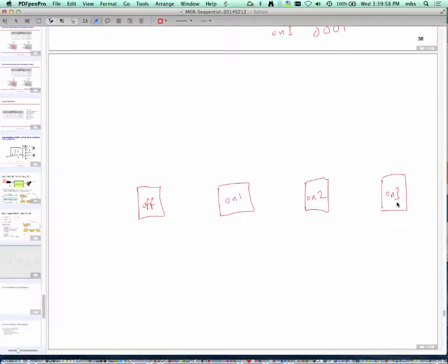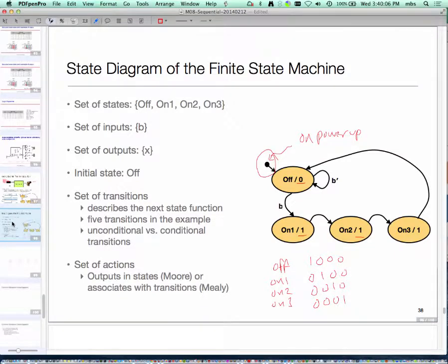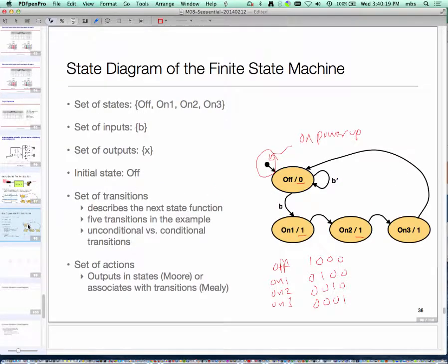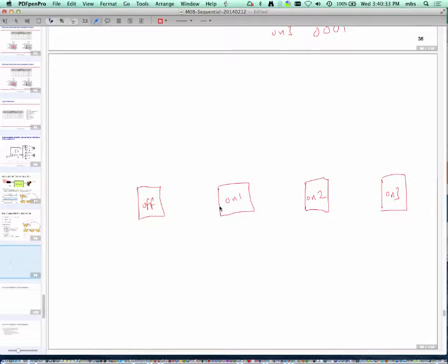Okay, so now the first thing we have to do is make the transition logic work. Let's go back to this diagram and look at on 2. The flip-flop corresponding to on 2 is this one. What do you think its input should come from? When should the system be in on 2? Looking at this, the only way is if currently it's in on 1. So we are basically going to have a straight line going from here to here.